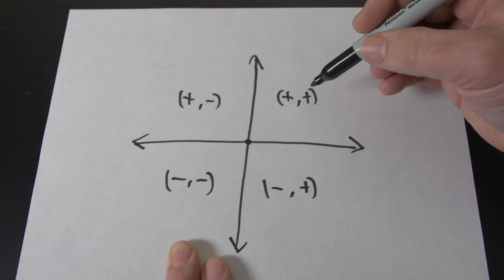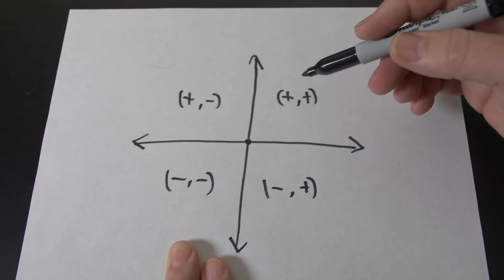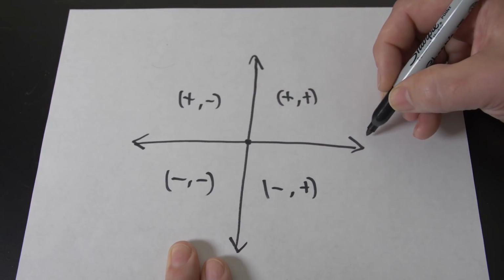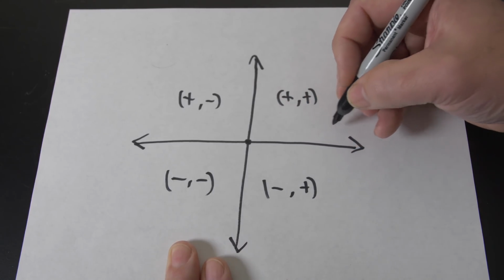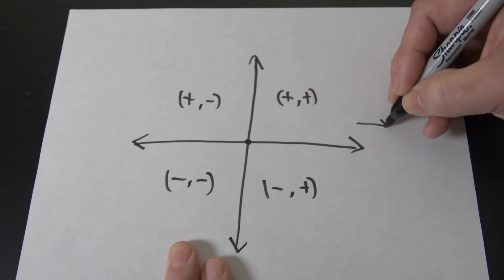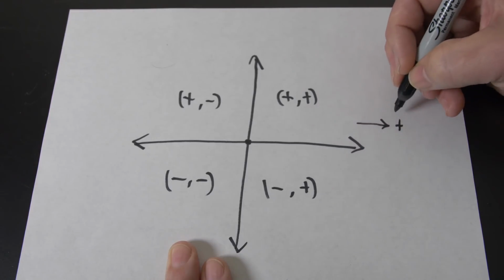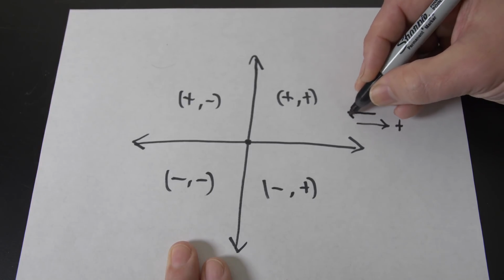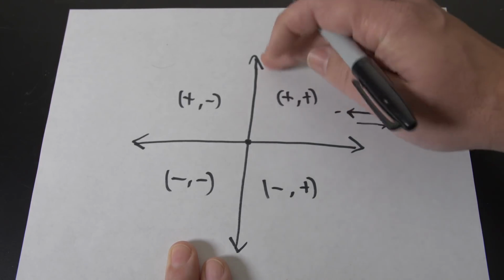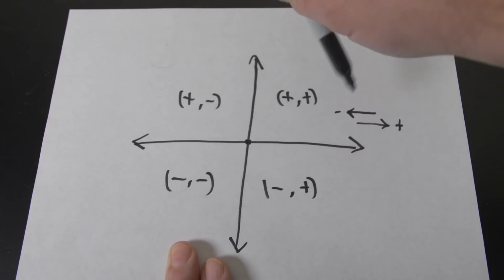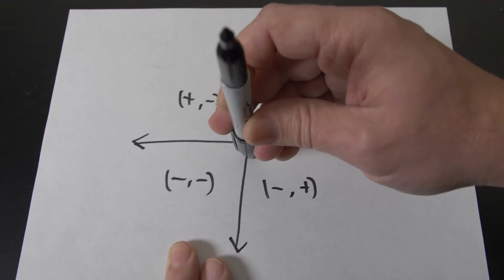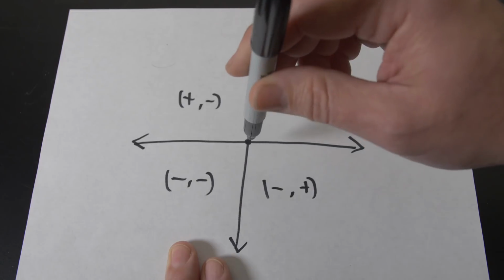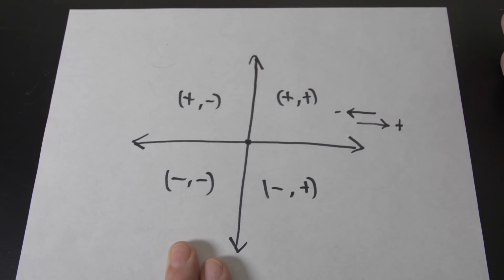Anyway, you need to understand this because you need to understand the movement of your machine. If you are at 0 and you start moving along the x-axis, you're going to see numbers that are increasing. So that is a positive movement. So this direction is a positive movement in the x direction. And if you are up here somewhere and you're decreasing, your numbers are getting smaller and smaller, that's a negative movement in the x direction. And of course the same is true for y. That's a positive movement in the y direction, that's a negative movement in the y direction, and in z towards the camera here, that's a positive movement in z, and away from the camera back towards the origin, that's a negative movement in z. So that's how you do that.